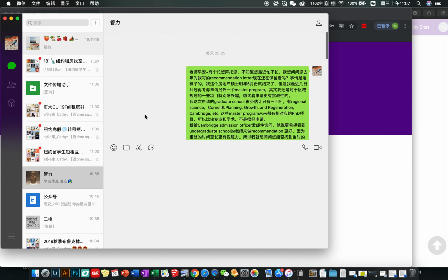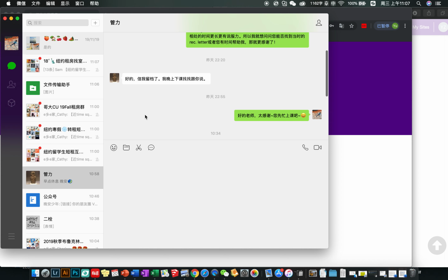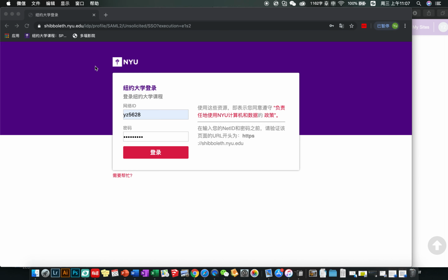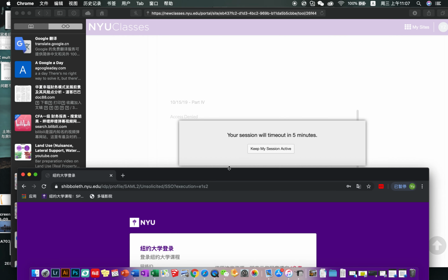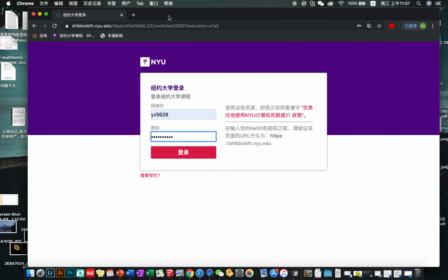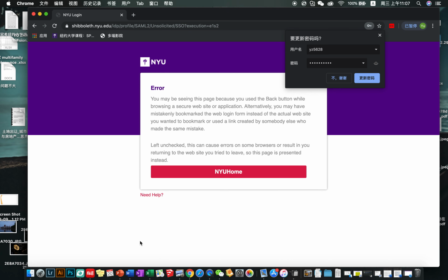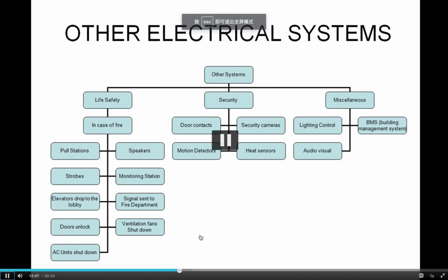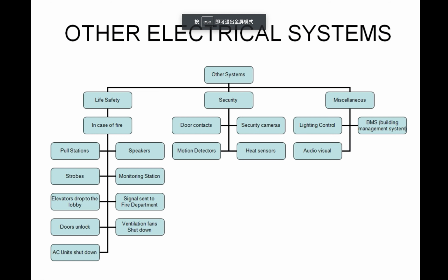All right, so other than the typical electrical systems that we've talked about already, things that you would need within a building include a life safety system, and this is all those things that are critical for emergency services. Having pull boxes for the fire alarms, speaker systems that can direct you in an emergency, strobe lighting, and emergency lighting that shows you where the exits are for the stairs, that provides enough power for elevators to get to the lobby should there be a cut in electrical power, so everyone can get out of those elevators and escape.